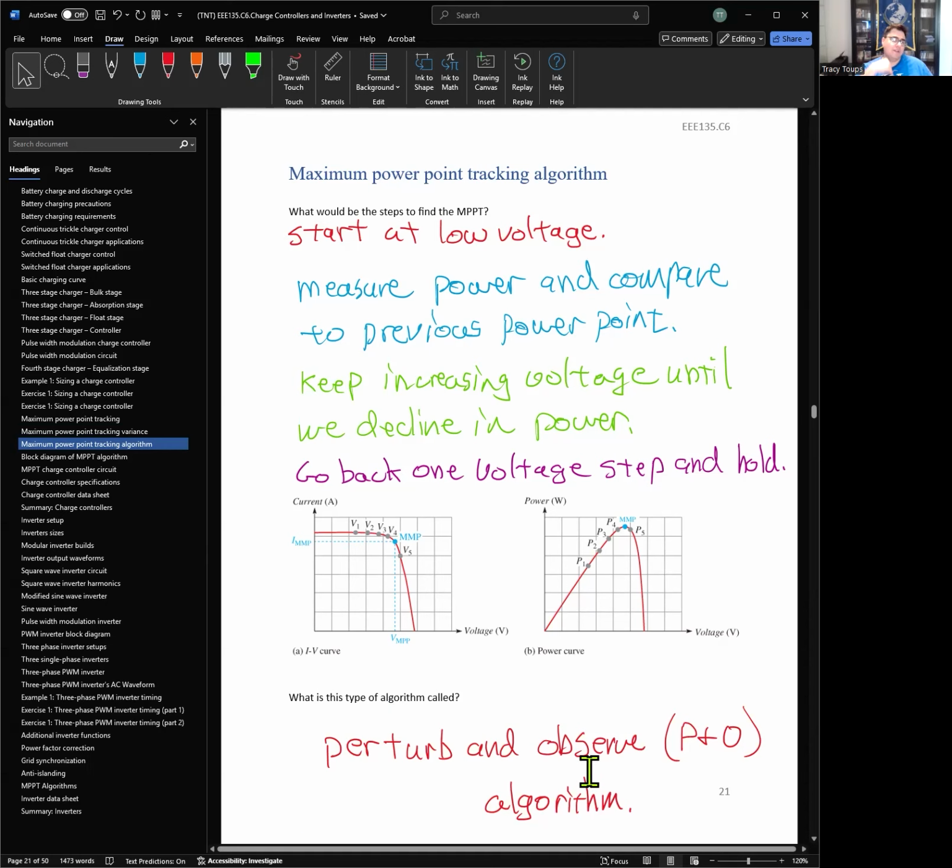So you have a system, you're modifying it a little bit, you're increasing it just at maybe 1 or 2% and observing what's happening, and we're just going to incrementally, safely crank up to a better power rating until we hit the maximum. Okay, so this is basically a giant while loop that consistently happens with an if statement attached to it, and you're just going to run this in your microcontroller over and over again until you get to the maximum point.